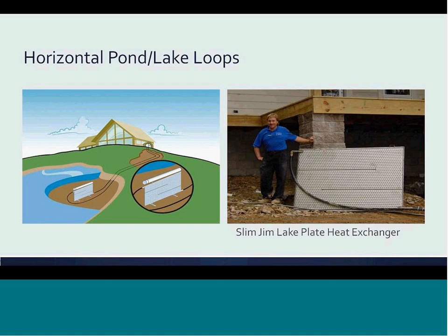Another way of providing heat transfer between a pond and a building loop system is to use a plate heat exchanger. Obviously, there would need to be a reasonable location to secure this heat exchanger in the pond, such as under a diving platform or tied to a pier.